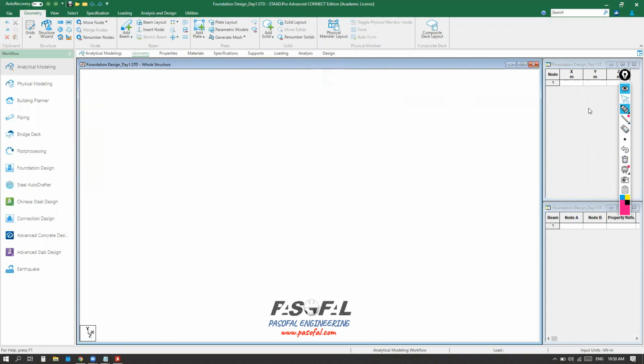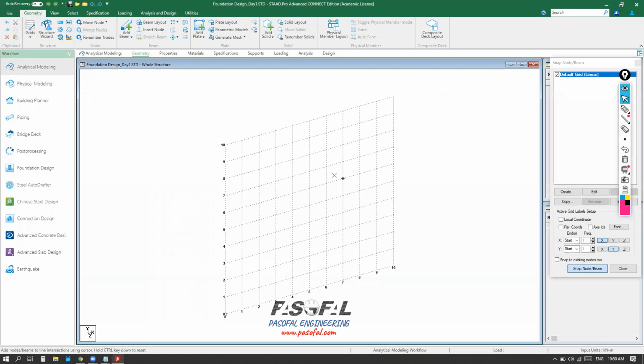Now let's start from geometry. From the geometry, the first option, I will go to grid. If I open this grid system, the first one is beam grid. Just go to beam grid. Right now the command is active.